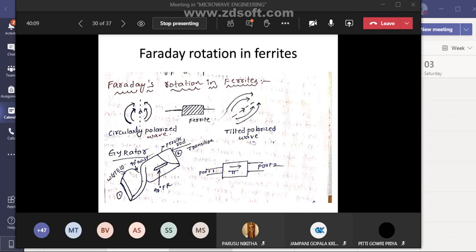It has a relative phase difference of 180 degrees for transmission from port 1 to port 2, and no phase shift for transmission from port 2 to port 1. It consists of a piece of circular waveguide with a transition to a standard rectangular waveguide at both the ends.